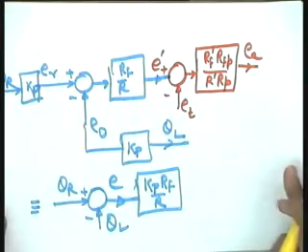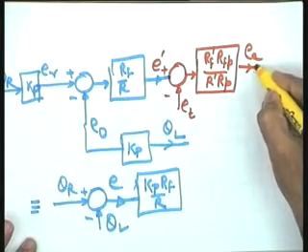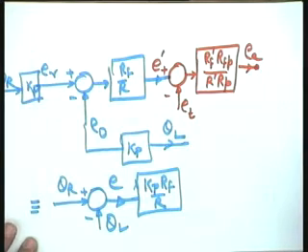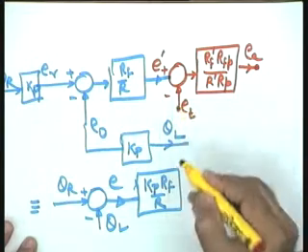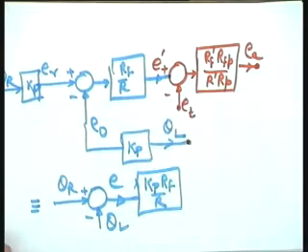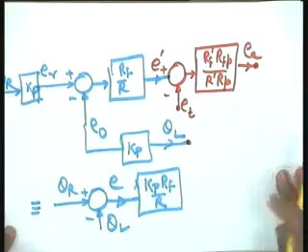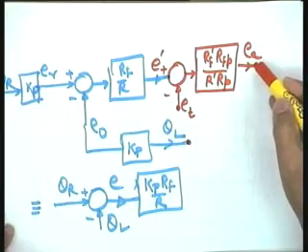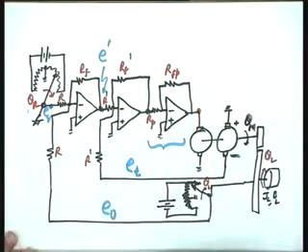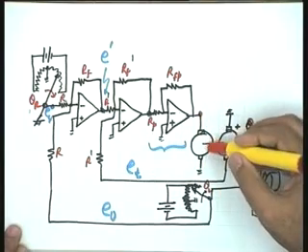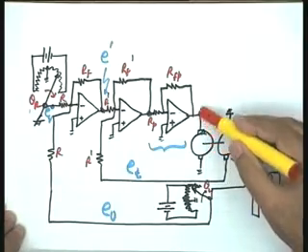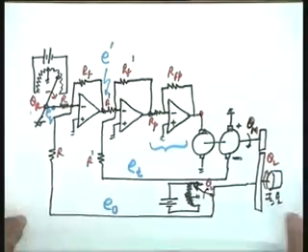Since on this slide there will not be space, from this armature voltage I will continue with my block diagram, but keep in mind that I will have to generate signals Et and theta L, so that the complete block diagram can be drawn. So Et and theta L I will generate from a block diagram which I take as a continuation from Ea. So this Ea has come at this particular point. Ea is the voltage which is available to the armature.